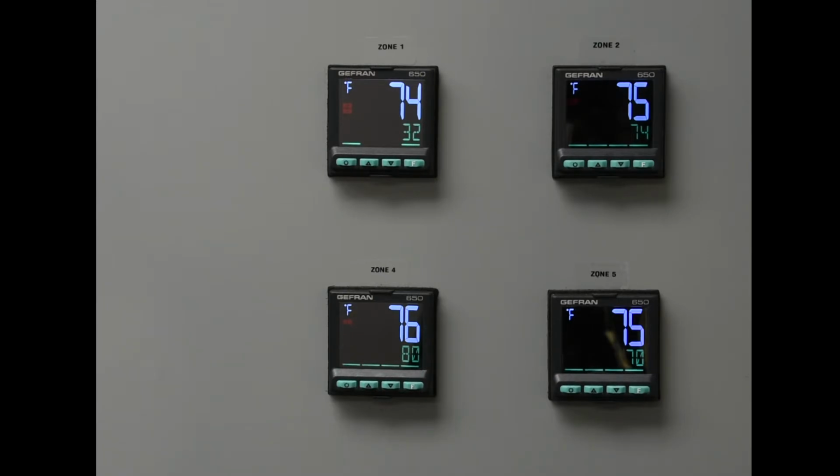Creating a ramp soak program. Programming note: up to 12 different steps can be created. Up to 4 programs can be stored with each comprised of between 1 and 12 continuous steps. For example, program 1 can start with step 1 and end at step 2. Program 2 can start at step 3 and end at step 5. Program 3 can start with step 1 and end at step 5.